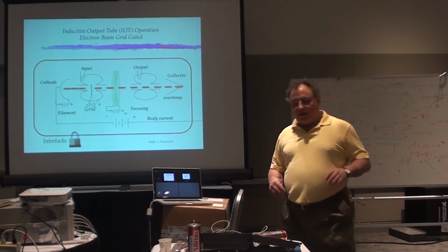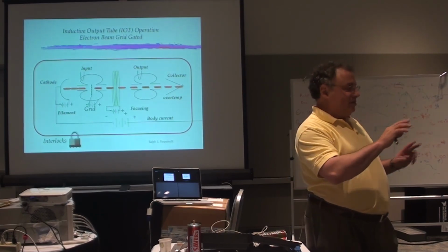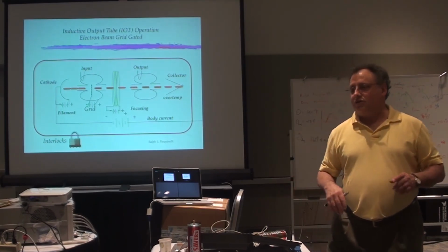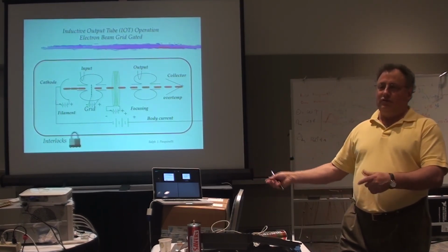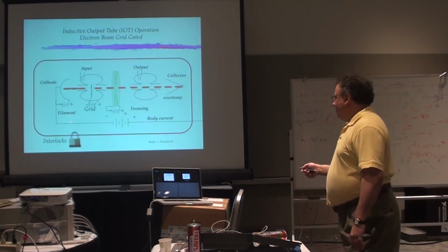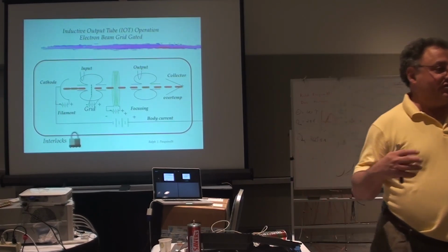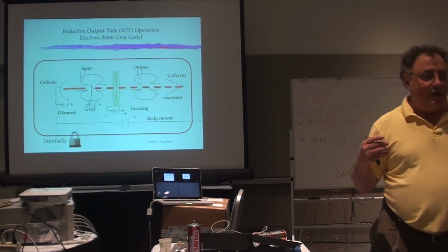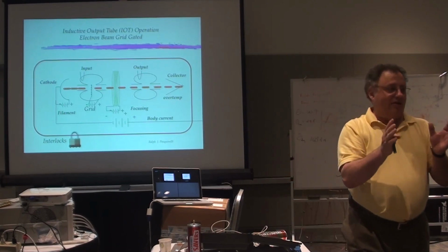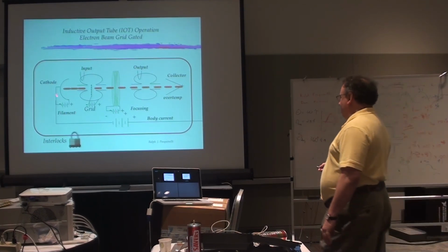If you want it to be clean, and remember, I think some of you were looking to see if you saw any 60 hertz sidebands on any of the signal generators. That's because if the power supply on your signal source is crappy and plugged into the mains, and you don't filter the 50 or 60 hertz out, that's going to come in there and put modulation. Well, the same thing will happen here. If that filament supply has power supply filtering issues, it's going to modulate the electron beam jumping off the cathode, and that modulation is going to carry through on all the cavities because the modulation is so close to the carrier that the Q of those cavities is not high enough to filter it out. So cleanliness in your power supplies is absolutely essential.